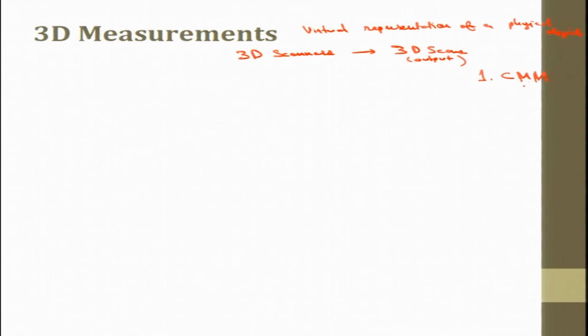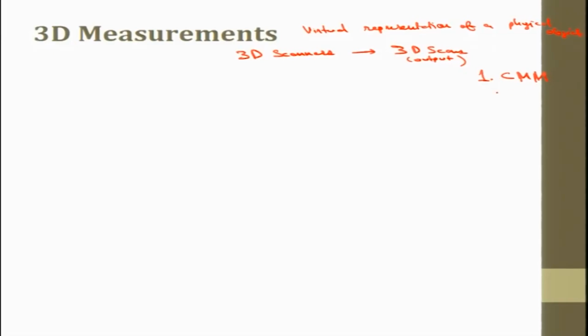Coordinate measuring machine. In this, arms can be equipped with either fixed probe or touch trigger probe heads. It is also possible to mount a 3D scanning head on the CMM. So, we will discuss this. There are many advantages, that many different tools can be mounted on the portable CMMs, making it possible to easily integrate scanning and probing. Limitations are also there. Portable CMMs need to be fixed on the surface, so they use a physical link. We do not have a portable machine, we have a full-fledged 3D scanner, not a very big industrial size, but for research it is quite capable of producing the outputs that are required. Also, we are doing some industrial consultancy here as well.